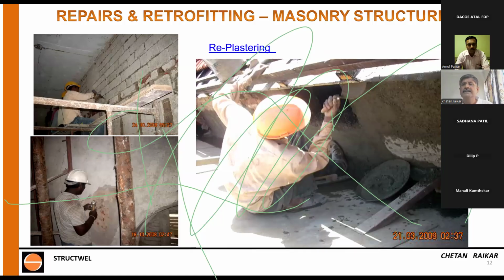Yeah. Use the cheapest material, because in civil engineering, the industry looks at us for economical options. So we try and use the best. That's why I said fly ash. Fly ash is what? Zero cost. It's a byproduct. It's a waste material actually. So if we use 20%, 25% fly ash, see what we are trying to do by addition of fly ash or this, we are trying to curb the shrinkage cracking. Simple. This is in replastering.